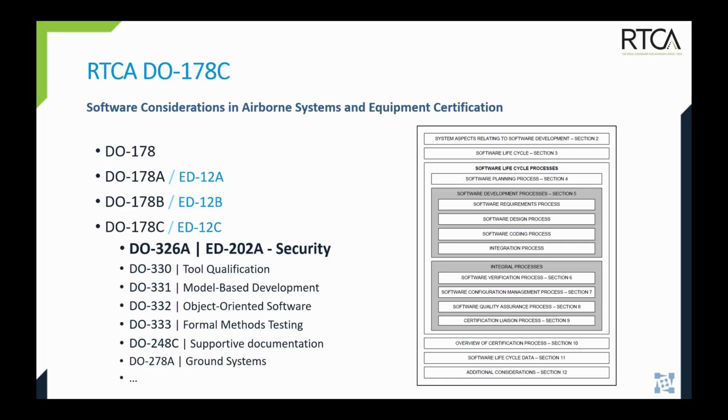Today we are at revision DO-178C, which was released in January of 2012, and this revision will be the focus of this presentation. You also see in this slide the European equivalent from EuroCAE. This is because the standard has been a continuous joint effort between RTCA and EuroCAE. Now, DO-178C made a lot of clarifications to remove imprecise wording around DO-178B. But the major adoption brought forward was a modular approach to supplemental guidance documents.